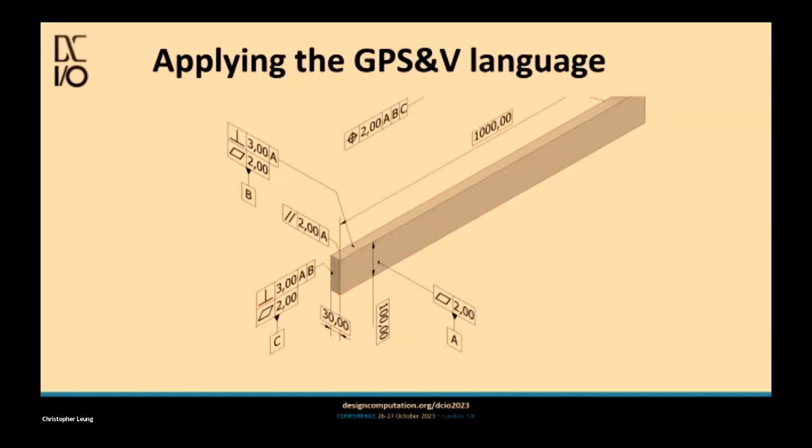And you can build up a complete specification for the location, the allowable variation in dimensional size, and the tolerance and geometric form to completely make a part testable that allows for deviation and focuses on the functional and critical features of the part, which are usually where things join.